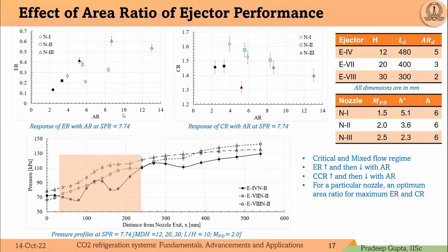Here you are saying that this is mainly for balancing loads, especially for applications where we want to use both the heating and cooling effects. So the motive flow is also part of the design, and the suction flow also affects the evaporator load. Can we tailor the operating conditions to have any combination of primary and secondary flow for a given motive pressure and for a given boost?